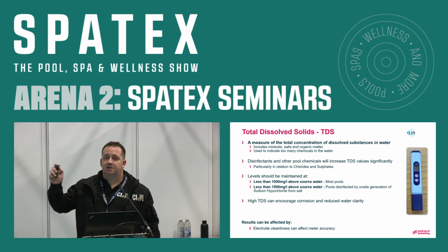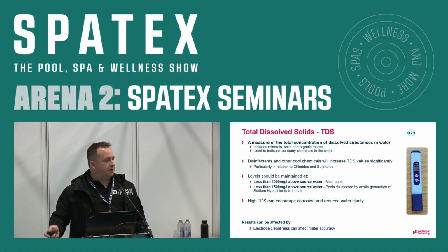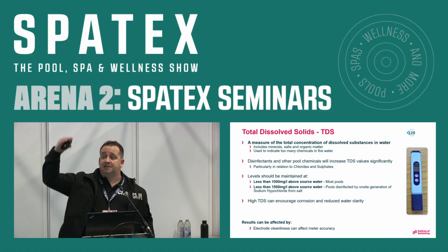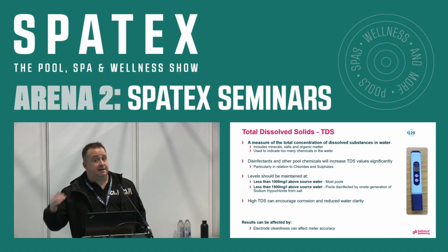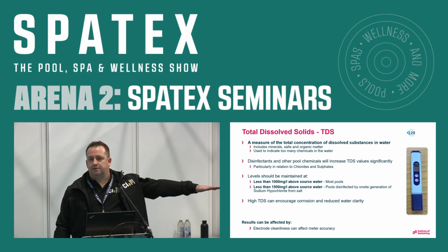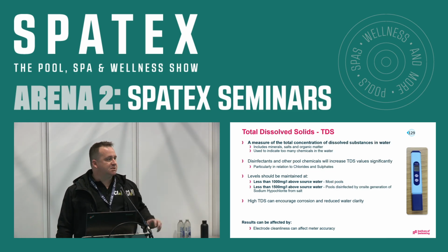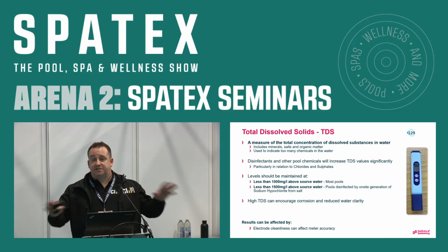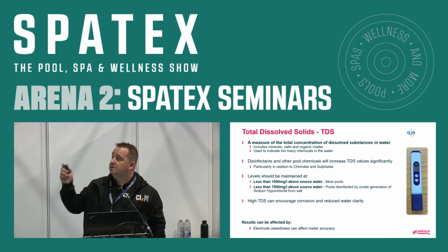Again, this is a weekly test to keep an eye on. It'll take you months to build TDS up, and it'll take you months to bring it back down again. So if you do a TDS test and you've got problems, you've got to look long-term to bring it down. Look at the operation, how we manage the swimming pool. And I know this might irk some people: backwashing doesn't fix everything. So please don't resort to backwashing just to fix everything. Dump water, by all means, but don't always backwash.